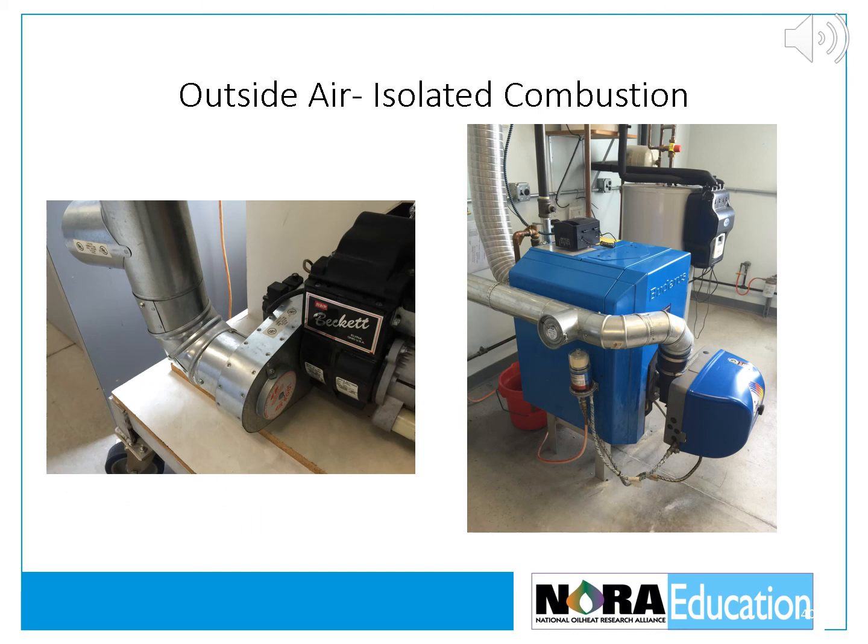This slide shows various ways to bring outside combustion air to the burner. The size of air infiltration heat loss depends upon the on-cycle airflow through the heating unit and the draft regulator, as well as installation factors such as the location of the heating unit within the building.